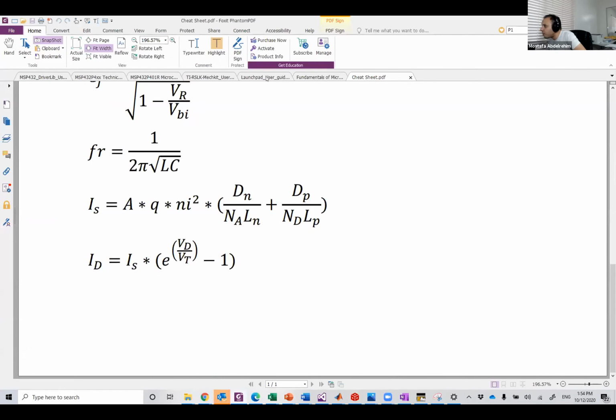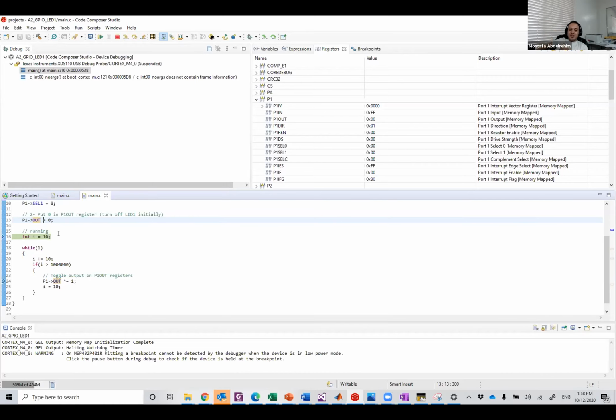But since we are not using the other 7, we don't care. What we care about is whether pin 0, the first pin, really has 0 or not. Here we set it to 0, and as collateral damage, we are also setting the other 7 bits to zeros. You understand? So is it not initially set to 0?